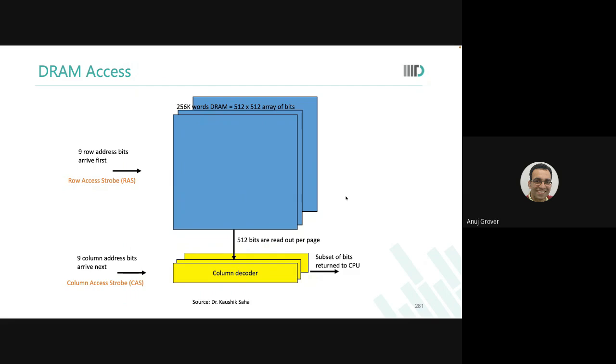Are you able to see this? In SRAMs, bit lines actually need to develop only about 50 millivolts and your sense amplifier will work. And bit lines can be reset, because the read will not disturb the stability of the cell.